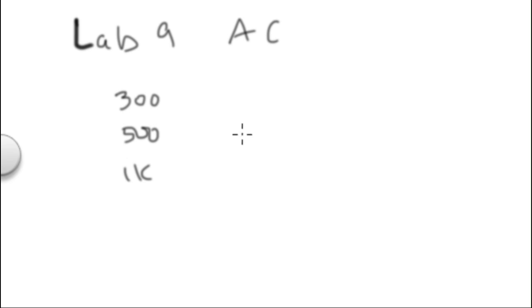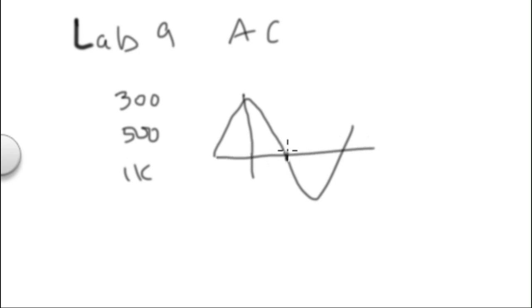What you're going to see is you have your input waveform, and then you have an output waveform that starts to shift, and it goes down. If this would be your 0 starting point, and this would be 90 degrees, your output waveform is going to shift, and it's going to have its peak someplace over in here. So we want to measure that shift, from here to here is 90 degrees, and if our peak hits right about in here, it's that percentage of 90 degrees.